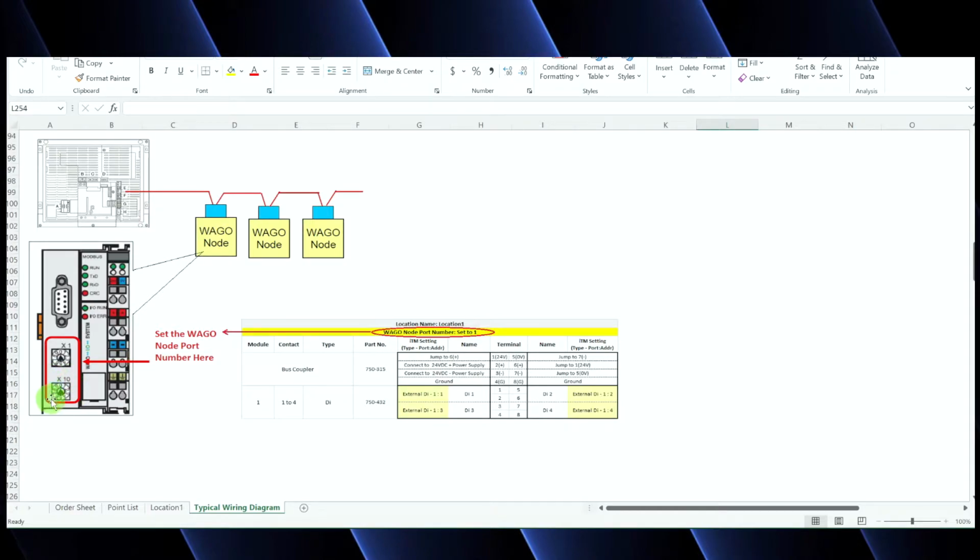Okay, so you're going to have port 0, which is in the 10s column, and then you're going to turn this to a 1, which is going to be on the 1s column. If you were to change this to a 1, this would be 1 times 10, so it would be 10 instead of 1. So make sure you address these rotary dials properly.